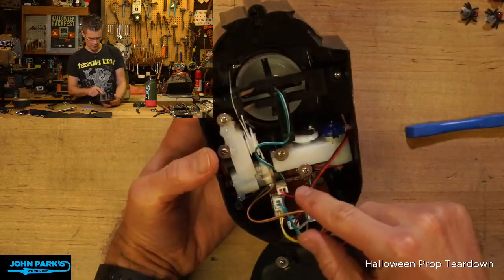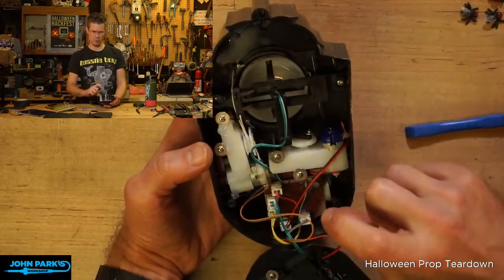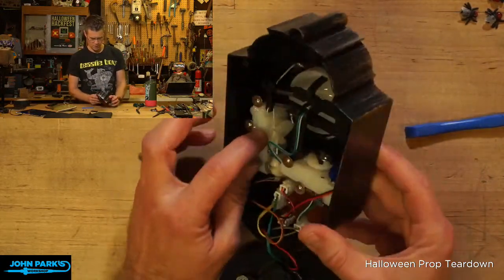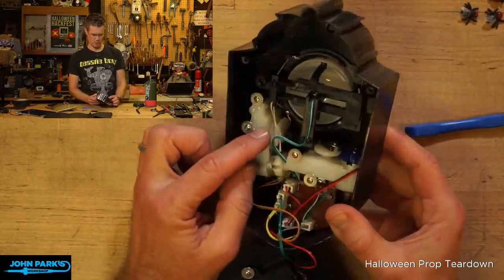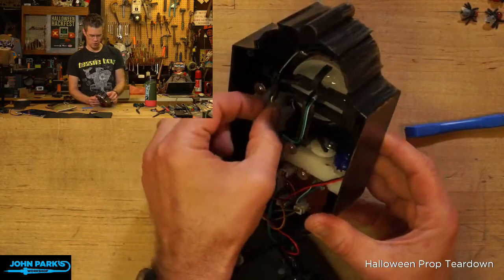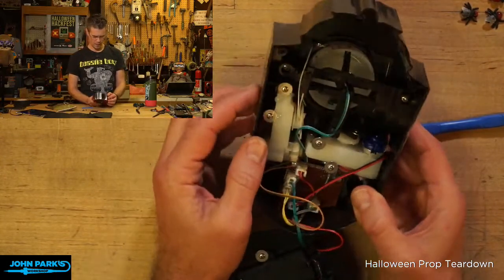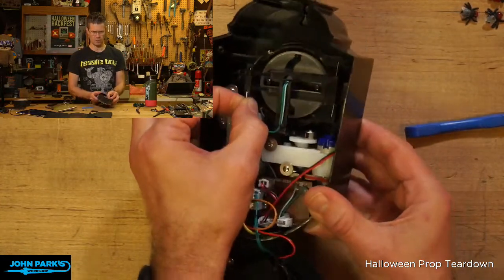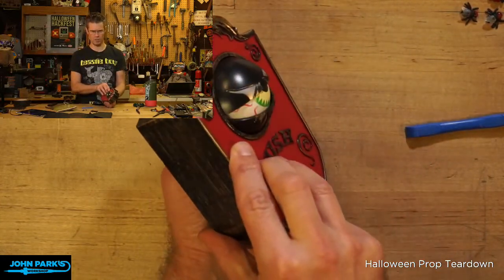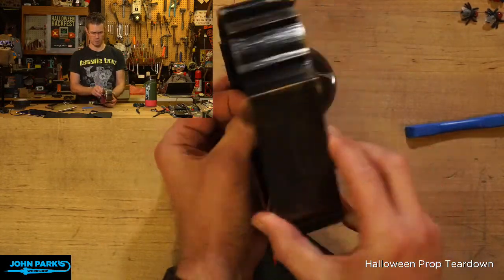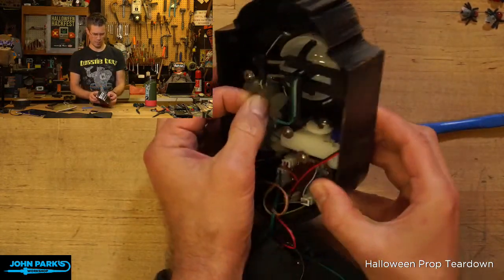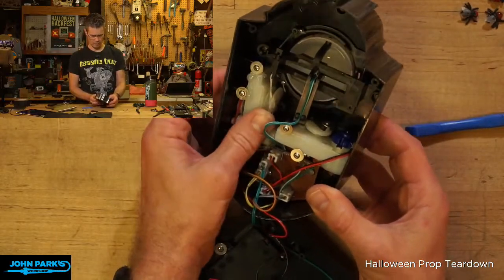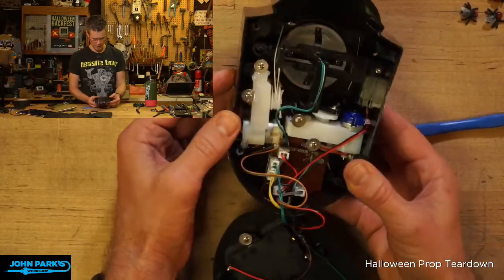This other one is what just yanks open and closed the eyelid. So actually it yanks it open, and what it has is a big sort of semicircular cam and a string, and it pulls on both of these to yank the eyeball open and closed. So as those strings pull, you get eyeball open and close. It pulls both of them at the same time, which is a little hard for me to do with my fingers. And so we'll take a look at how that works.